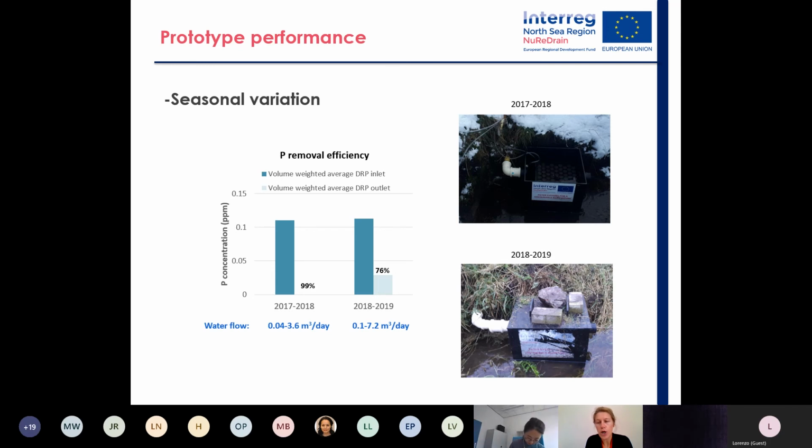Then how long is the retention time? You mean the reaction time within the filter, how long is the water remaining in the filter? Minimum 1 minute. Of course, it also depends on the flow rate. The more water is coming in, the shorter the contact time.